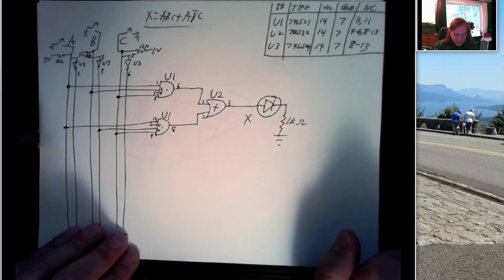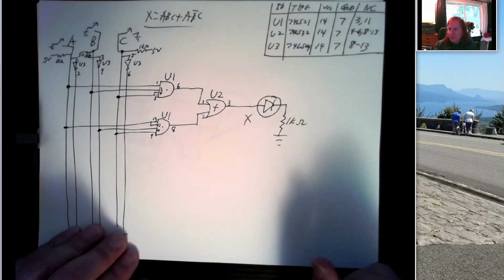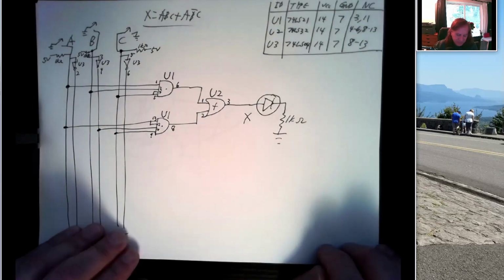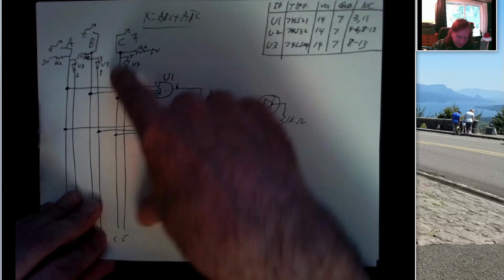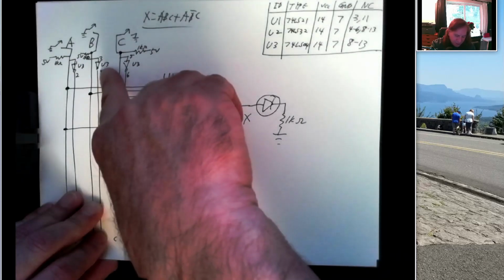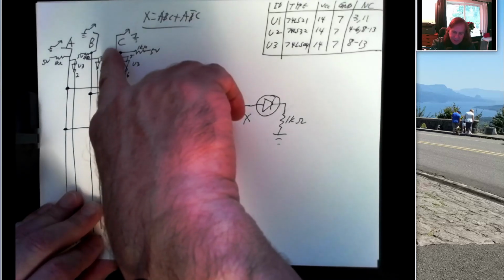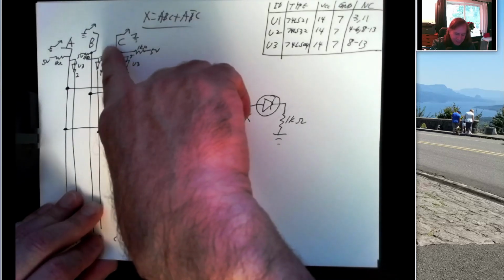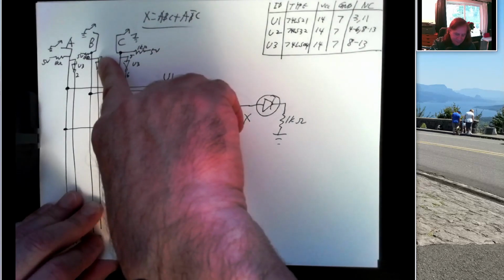And eventually we're going to find some point where we say, hey, this should be 0, but it's a 1. Or it should be a 1, but it's a 0. And there's some undeniable reason for it. For example, the output here should be 1, but it's a 0. But the input is a 0. So this is an inverter that's got a 0 going in and a 0 going out. That's where your problem is.